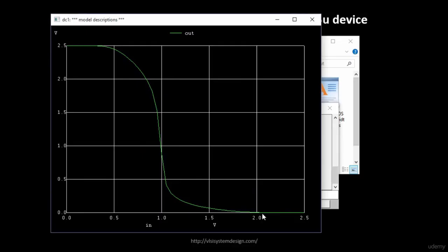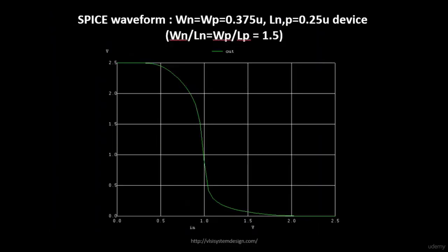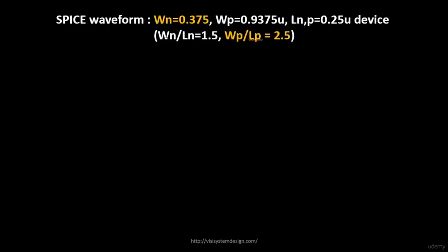For example, it will have the oxide thickness, it will have the threshold voltage under zero substrate voltage, it will have all your coefficients K1, K2, K3. If you go through this file, I'll upload this file, you will have everything which is related to this particular PMOS and everything that we discussed in our past videos. Okay, so this was about the model file, and this is what we have included in our netlist description. So let's look into the netlist first.